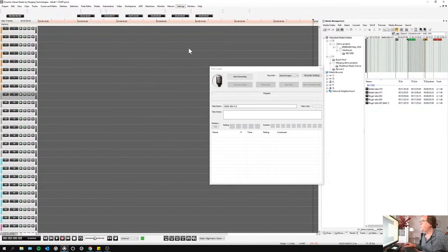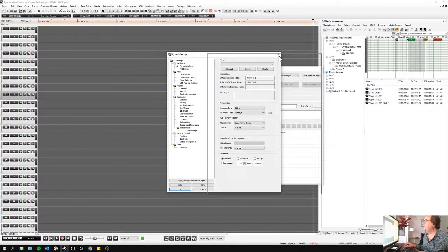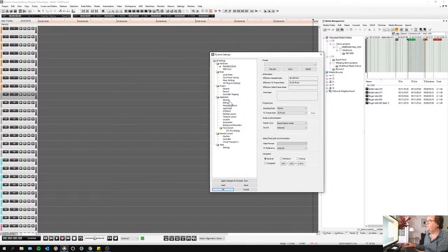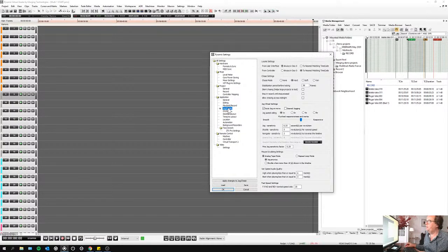So I go into old settings that you just saw up there. I'm just going to cover this so that you don't get confused, and I'm going to go into one tab here called jog and chase, and this part is very important, chase settings. So I have 4 possibilities of chase modes, so to say. The first one is not to chase, even if I receive some timecode. Hard chase, so basically it will really chase straight away to the incoming timecode.